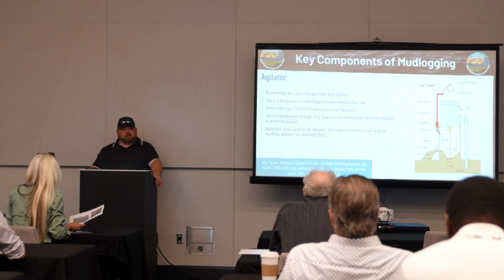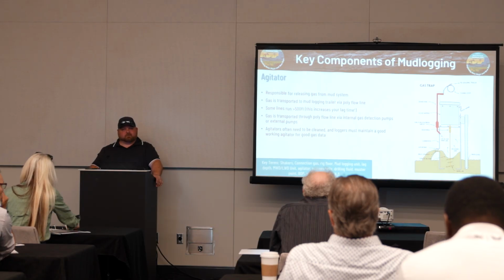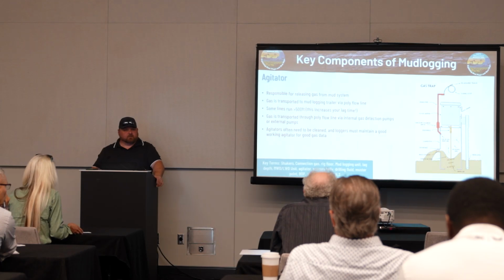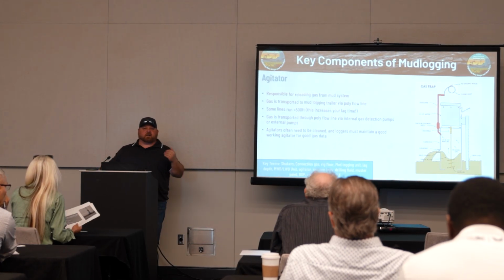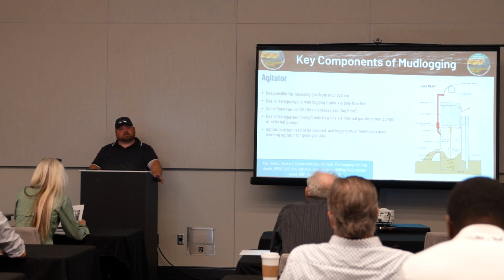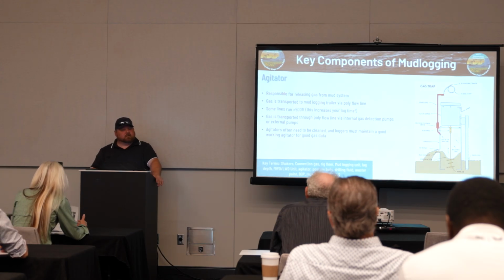Pumps nowadays are pretty good as far as speed and volume, so it doesn't affect it. But at 600-700 foot, you're starting to see an actual surface lag of the gas coming from the shakers to the actual detection system. We do have IR systems that are remote as well. Those are called pit roosters, the ones that we use at least.